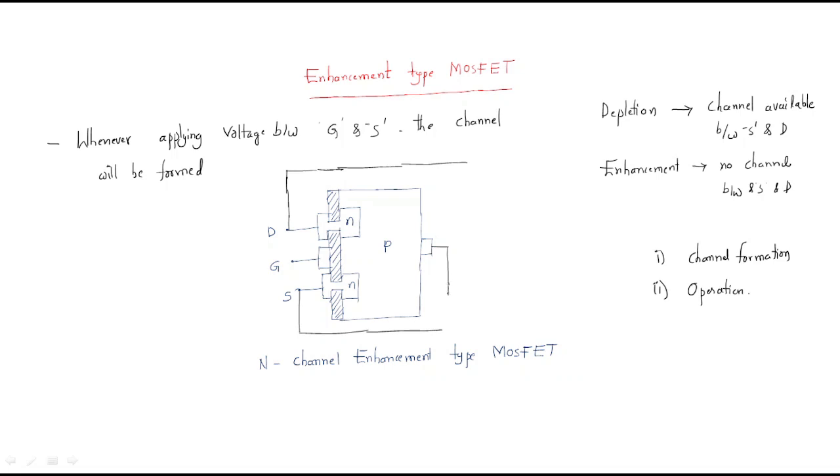This is an N channel MOSFET, that's why source and drain are N type materials, the remaining is the P type material, and the channel should be N type semiconductor only. And the drain should always be reverse biased, that's why we will give the reverse bias. This is the VDD, and we should apply it for the source normally.